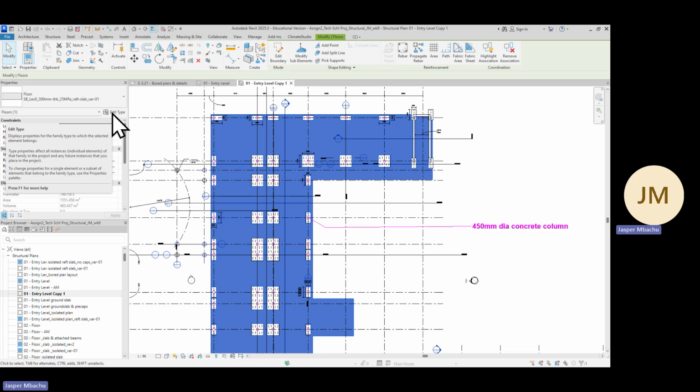It's always good, I would suggest, that any of these variations that we're talking about in the substructure, we mentioned X number of variations to the original design. Whenever you clone and you are documenting that aspect, always put underscore var 01. With that, somebody can associate what was there before and see what the variations are. So it's a good practice to do.